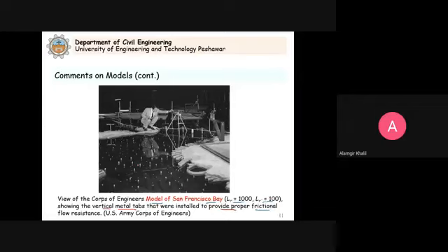That these vertical distortions disturb the circulation pattern. Now what happens is that these will disturb the circulation pattern. What we mean by this? The metal tabs will create large scale eddies, because when the water flows they will create eddies. So hence we must interpret mixing in distorted models with caution.